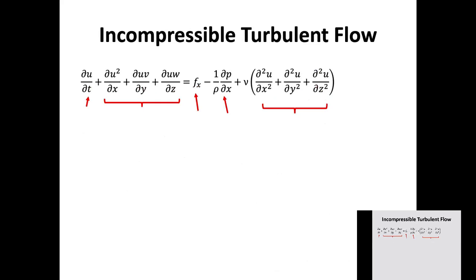Then we will look at how incompressible turbulent flow is. So that's your Navier-Stokes equation, if you remember. The first term gives you the local acceleration, then the second term gives you the advective acceleration, which is the spatial component, and then you have the body force effects, and the next one is the pressure gradient, and the next one is the other stresses, which is the stress component.